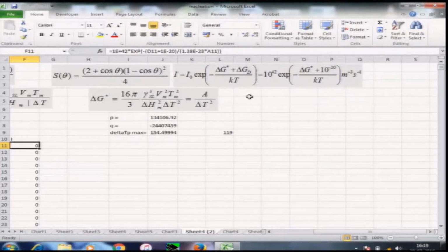The jump frequency will go down as the temperature goes down, simply because atoms do not have enough energy at very low temperatures to jump. So, the probability of a successful jump goes down, and the number of critical nuclei becoming supercritical starts to drop.